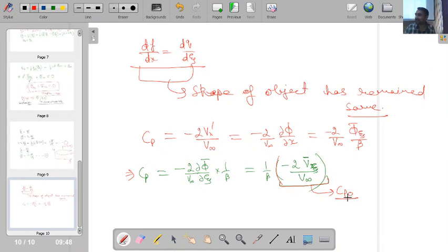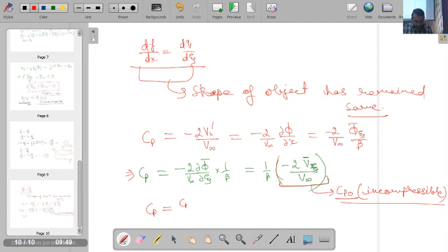Is this point clear? So now, whatever pressure coefficient we are getting in zeta eta plane will be nothing but for incompressible flow situation. So I can say that Cp naught is nothing but my incompressible pressure coefficient. Okay, so the compressible pressure coefficient Cp will become now Cp naught by beta, which is equal to Cp naught by, what was beta? Square root of 1 minus M infinity square.